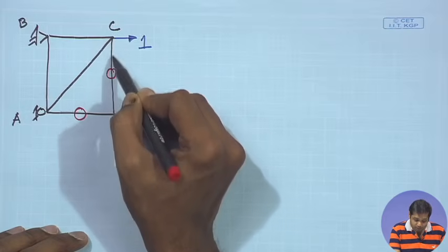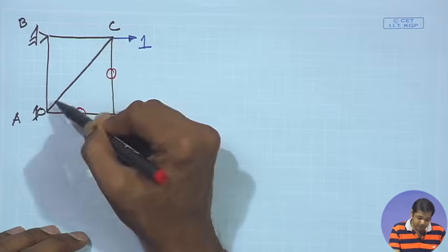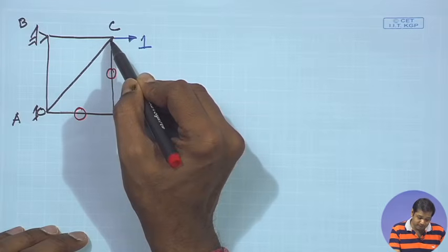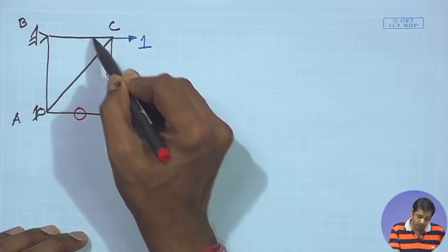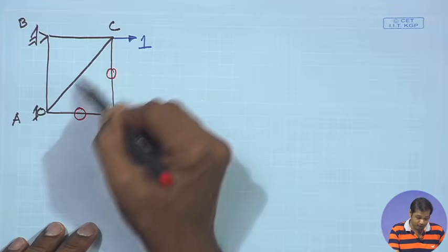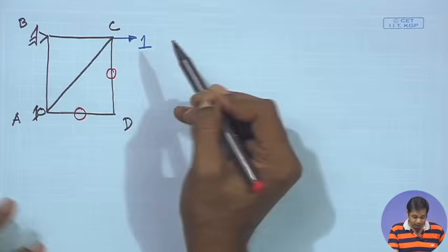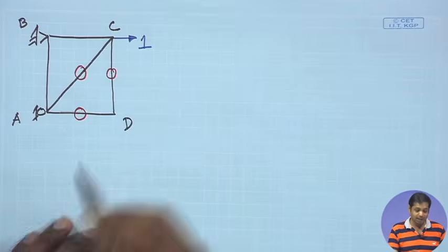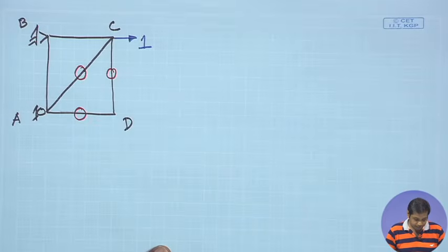There is no other member force in CA. Now, the force in member CA has horizontal and vertical components, but there is no other vertical load which can balance the vertical component of member CA. So, therefore, the force in member CA has to be equal to 0, right.